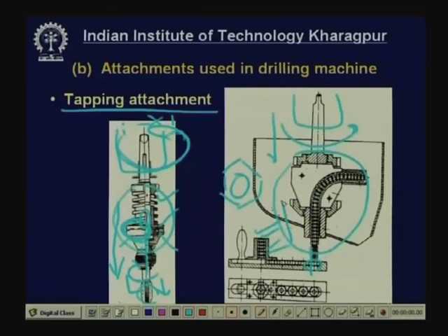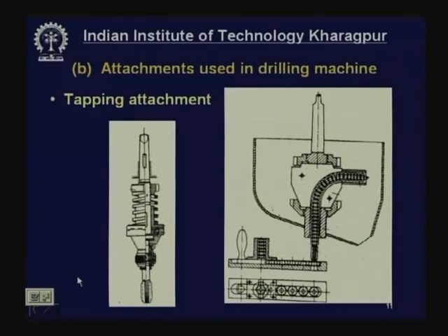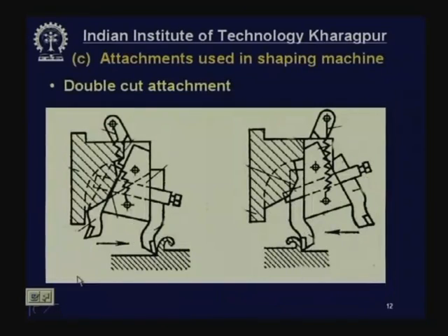After that, when this goes up, this nut will go up along the tap and reach here, and then another blank will come, another thread will be cut. So, all these nuts will be accumulated after thread cutting. But because all these things are rotating at high speed and this chute is fixed, by centrifugal force these nuts will be thrown out and all of them will be collected into a bin. So, this is a little faster production of nuts by threading by an attachment.